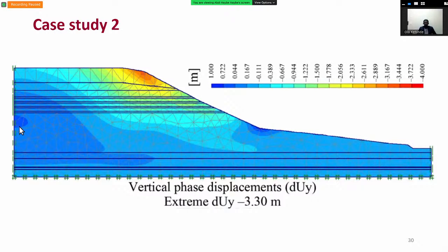Okay. In this model, the determination of the factor of safety is insufficient, like using the analytical method, but with the finite element method, you're able to predict the actual settlement based on the displacement and be able to optimize the way of reinforcement and also predict the failure mechanism, as well as use the field and laboratory tests obtained to better approximate the real behavior of the structure.